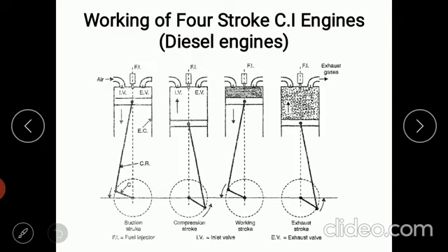Then once the combustion is initiated in one location, heat will be transferred to the remaining part of the cylinder by radiation and convection heat transfer mechanism. So because of radiation and convection, combustion will occur in different locations of the cylinder, just like exploding bombs in different locations.